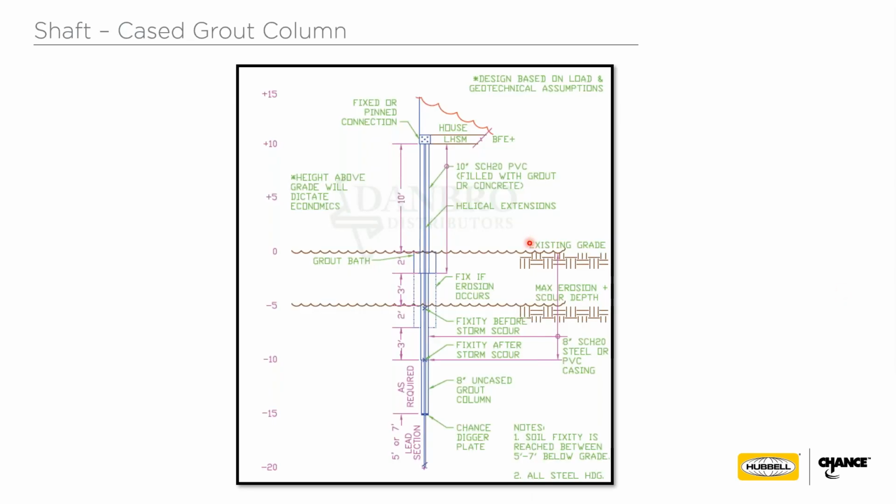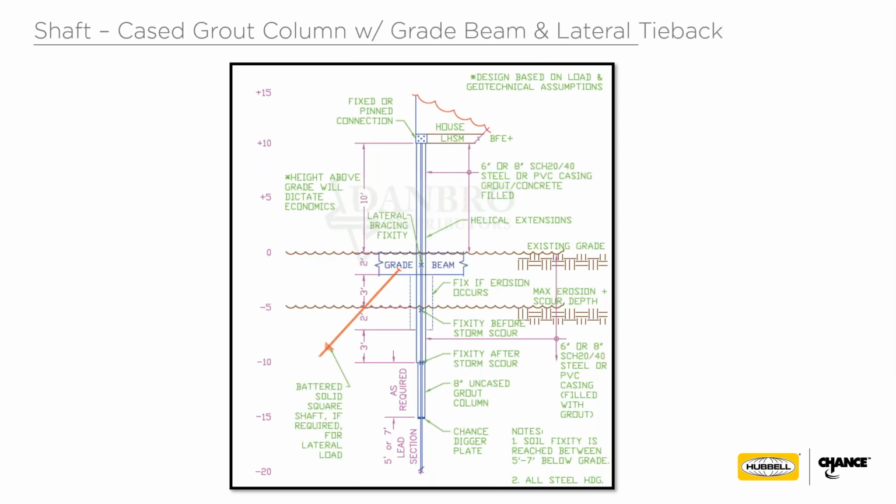So the types of helical pile solutions that I'm going to show you here are for structures that have to be simply vertically raised and then the piles installed underneath them. In other words, there's no room to move the structure. And so how can you do that? Well, in some cases, people just extend a helical pile, and above grade extend a pipe shaft or a casing in order to provide that support, not only for the axial loads, but also for the lateral forces.